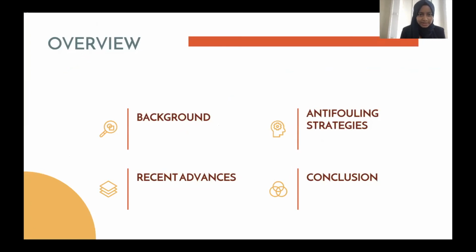So a quick overview. Basically, I've introduced membrane technology and why it is important and what the obstacles to it are. The obstacle is obviously the fouling that takes place, because of which we need to come up with antifouling strategies. So I talked about four different types of antifouling strategies that are in place, starting with membrane cleaning, which is physical or chemical, and second, modifying the migration of the pollutants before settling on the membrane surface and pores. Third was pre-treatment. I'm also working on one of the pre-treatment methods prior to membrane filtration. And the last one is membrane surface modification.